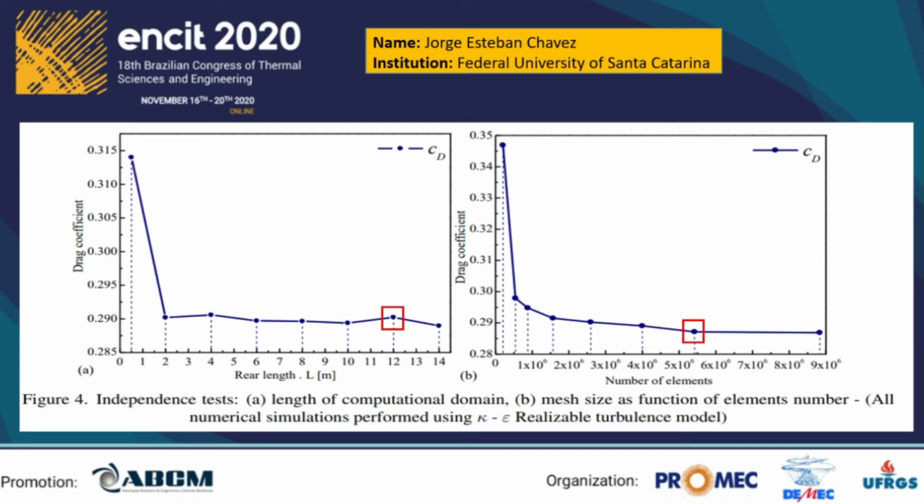the value of 5.4 million elements shows a difference of only 0.6% with respect to the previous value. It was selected for all numerical simulations in order to compare the numerical results of this work to the experimental data available in the literature.